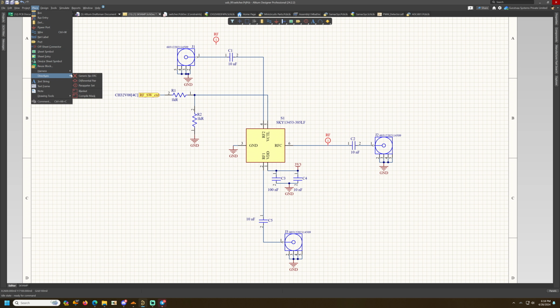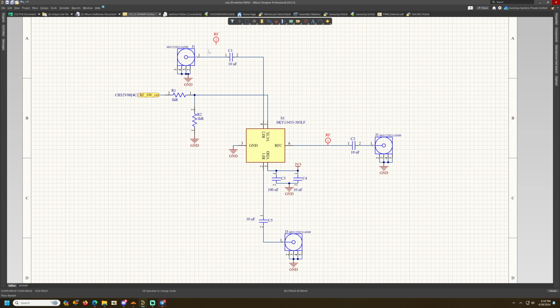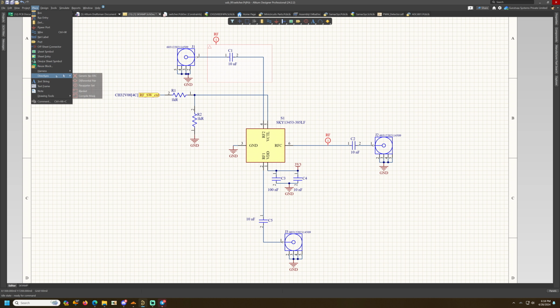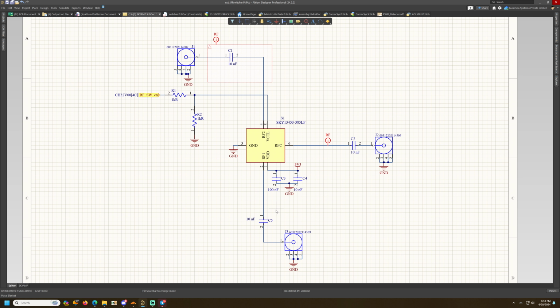Additionally, the datasheet also suggests that the V control pin can accept only a maximum of 3 volts, and for that purpose we have put a voltage divider to scale down the control voltage, which would normally be 3.3 volts level coming from the microcontroller. Unless of course we power the microcontroller with 3 volts, we wouldn't need the voltage divider.